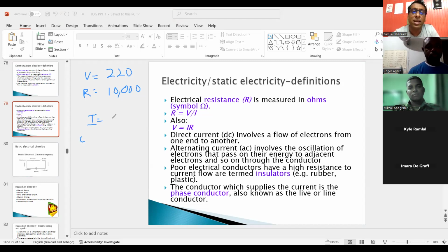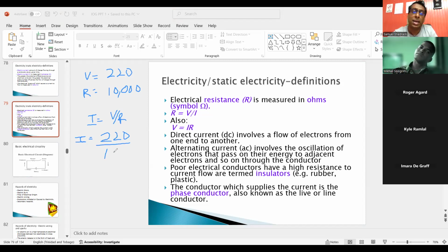It's very frustrating. Okay. So yes, exactly V over R. You take the voltage and divide it by the resistance, and what you'll get is the current in amperes. But there's a chart that shows you the effects of the current in the human body in milliamps. To get it in milliamps, you're going to have to multiply by 1,000, right?